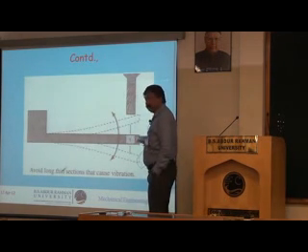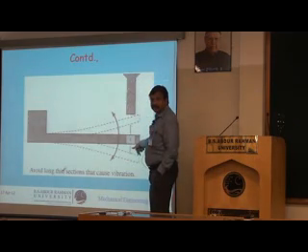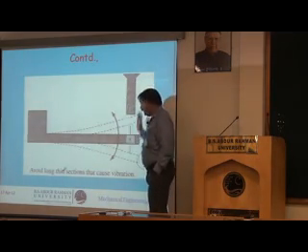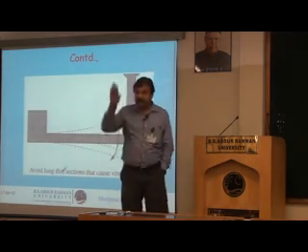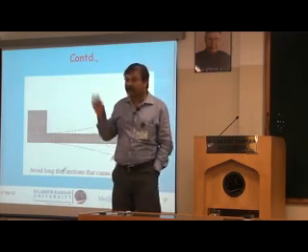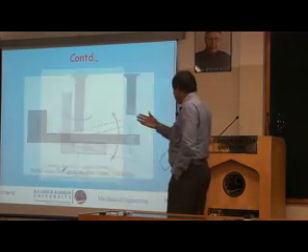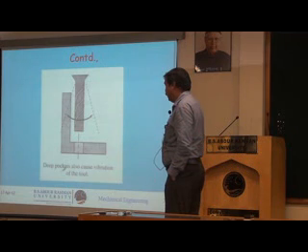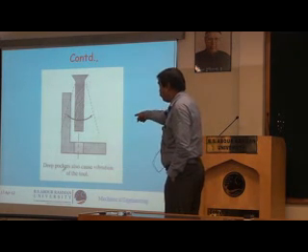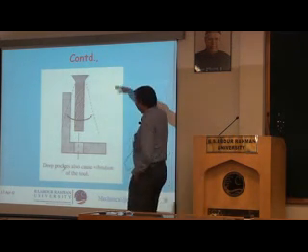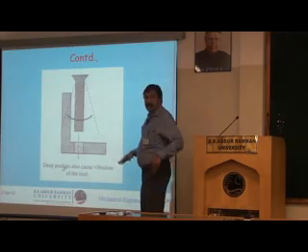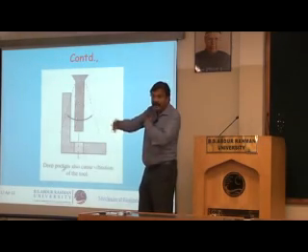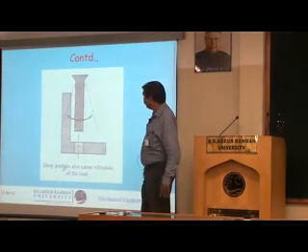Similarly, if you have a long thing, if you drill it, this is a long cantilever beam, under the cutting forces, it may get bent, it may vibrate, it may break. Next. Similarly, this is a very long tool, and a long tool may again vibrate. Next slide, please.